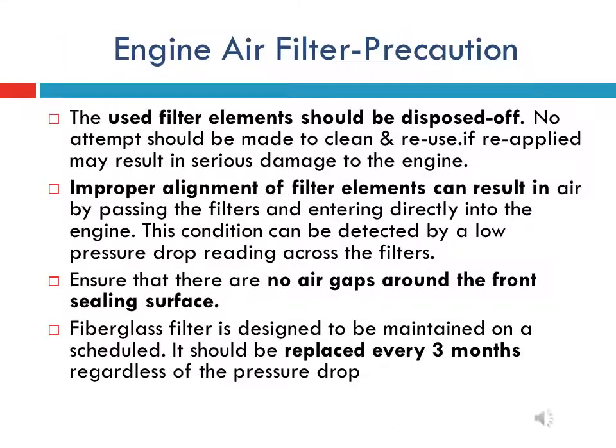Engine air filter precaution. Sometimes unfiltered air enters the engine, which may result in serious damage to the engine. So the following precautions are to be taken. First, the filter elements are to be properly placed and aligned in the filter assembly. Second, we have to ensure that there are no air gaps around the front sealing surface.